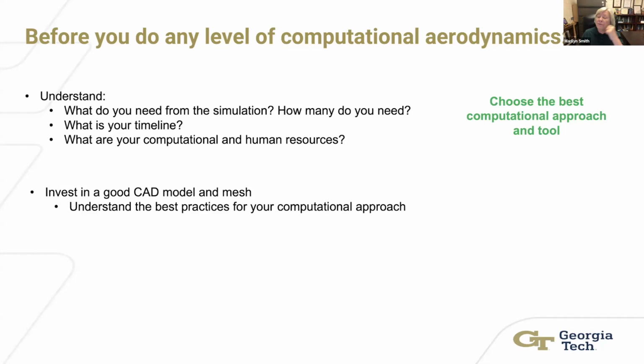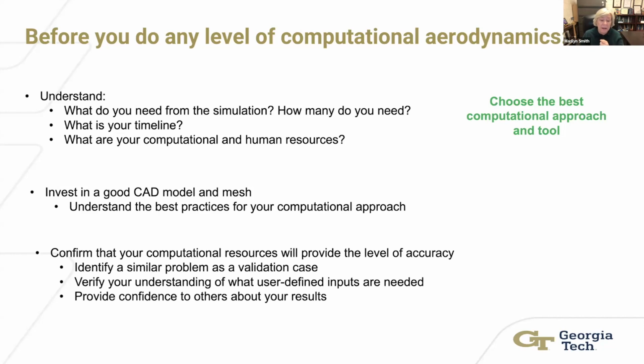See how well they've done. Is their accuracy the kind of accuracy you need? Use that to guide what you're doing. Then, before you make a whole bunch of runs, please make sure you're running your code right, whether it's a CHARM code, RCAS, or OVERFLOW, or one of these SU2 very complex codes. Confirm you're going to get the right level of accuracy.